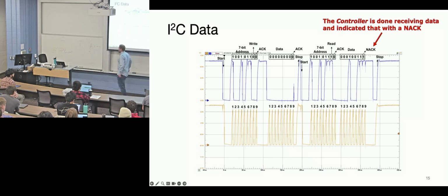Ah, okay. That's a good question. So this is just nuts and bolts, like talking back on a bus. But on top of that is what the chip does. So it could be that all zeros means go to register 0 and pull out data. So it could be like, here's the address of the device, and maybe this is the register in the device. I don't know. But your data sheet will tell you how to interpret these bits and what should happen. It's not defined by this protocol. It's just a transport layer, with what your devices do on top of it.